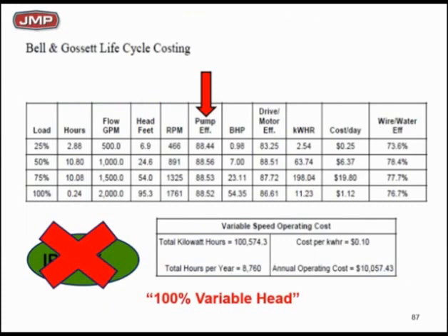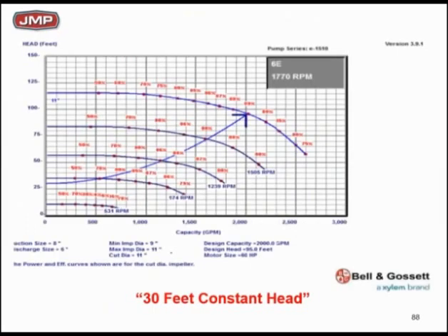We know that's wrong because you're going to need two-way valves. Let's go back and add a two-way valve. Same pump, same load profile. I'm going to say I need 30 feet of constant head. I'm going to have 30 feet of constant head out of my total. And you see back at 0 flow, my control curve goes to 30 feet. This is more like the real world.